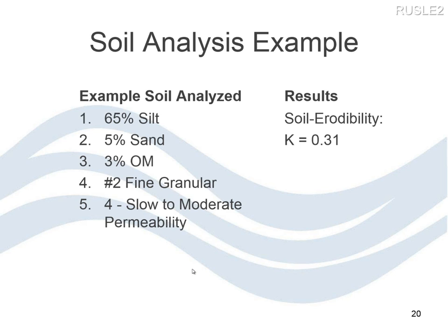Organic matter, we can get at in terms of a lab test. We can basically burn the soil off, and there's a standard lab procedure to figure out how much organic material is in the soil. The relationship between organic matter and K factor is that the more organic matter you have, generally the lower the K factor.